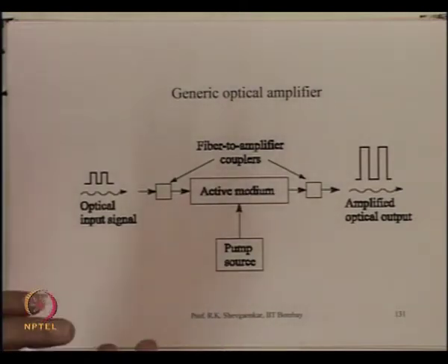and back. So essentially what we are looking for now, a material first of all which can have the energy levels corresponding to those wavelengths or frequencies which we want to amplify. So we have seen in laser that if you are having the difference in the energy levels equal to the energy of the photon, then the stimulated emission can take place and the photon flux is amplified. So firstly what we have to do is we have to identify the material which have proper energy level differences corresponding to the frequency of the signal which we want to amplify. And that's what essentially is done in this erbium doped fiber amplifier, EDFA.